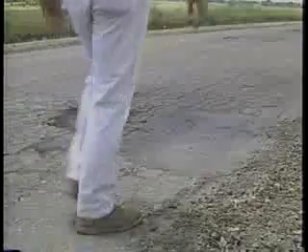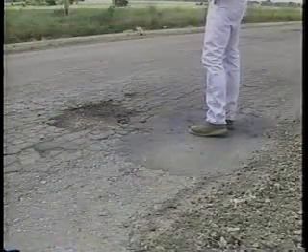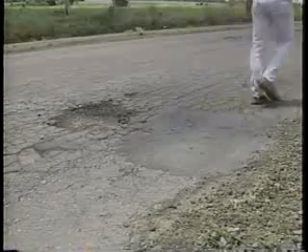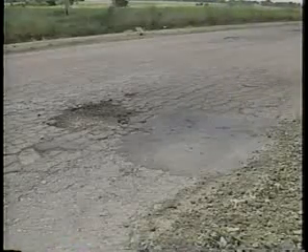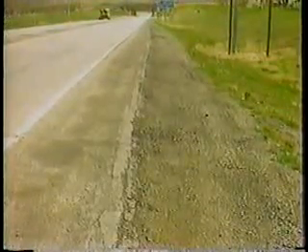That surface may be an aggregate base, a previous surface treatment, or a plant mix course. Part of surface preparation is the initial inspection of the road to assess its condition and determine if a seal coat is the proper maintenance treatment to use. Drainage conditions should be part of this initial inspection. See that any problems are corrected before application of the chip seal.